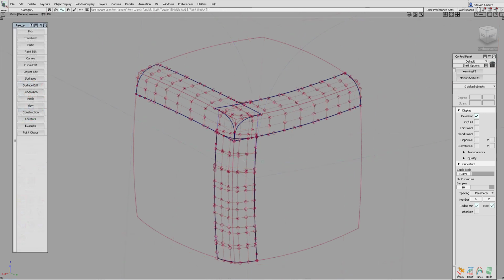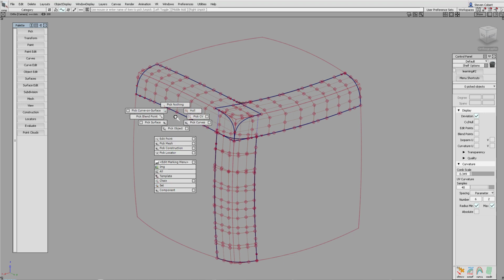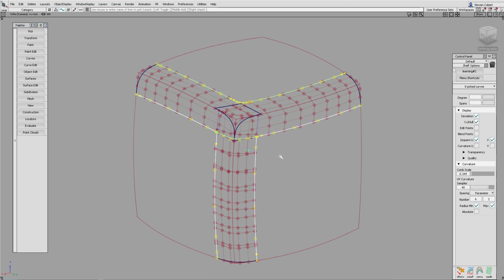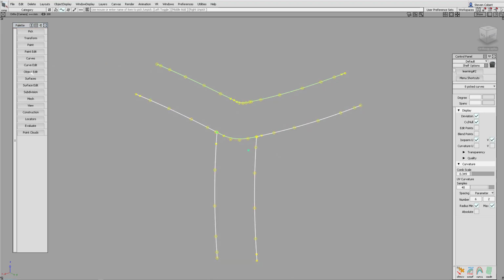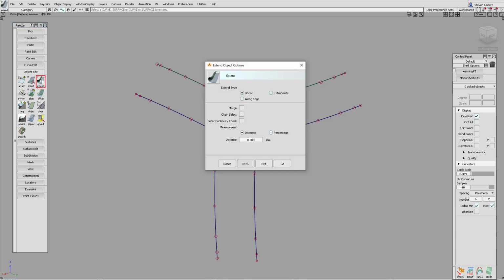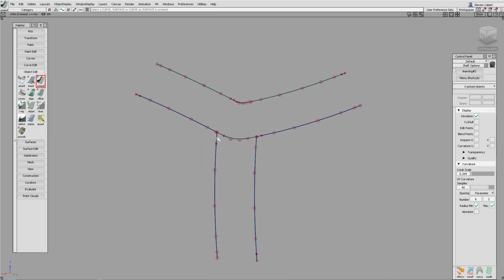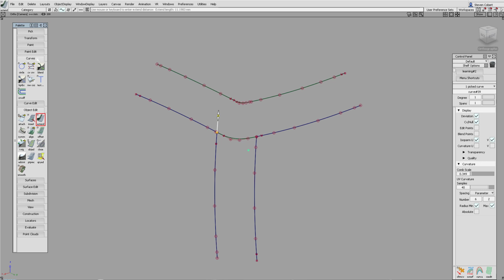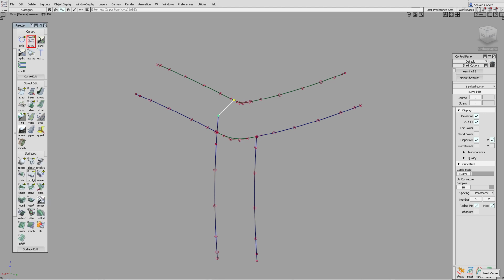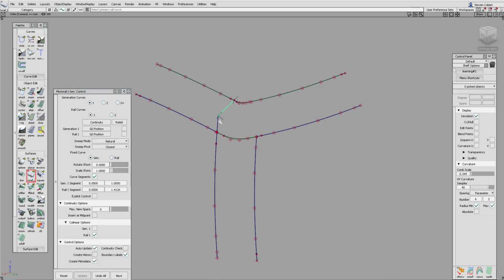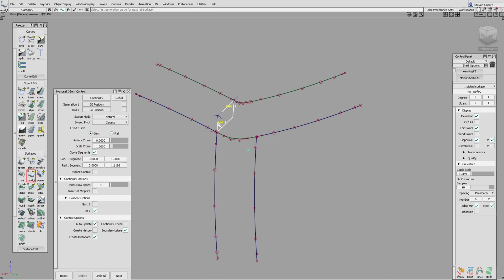The left and right hand fillets now need to be trimmed. To do this, we're going to create planar cutting surfaces which are tangential to the edge curves. Firstly, we'll extend the edge curves with linear and no merge. This creates a line which is tangent to the end of the curve. Then we'll connect the end of this line to the end of the top curve with another straight line. To create the planar surface, we can use the rail function. This surface will be used to trim the fillet.